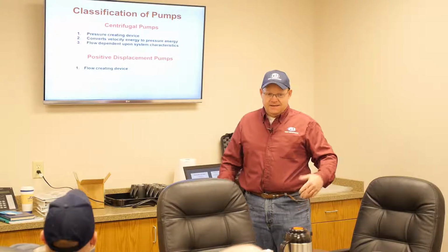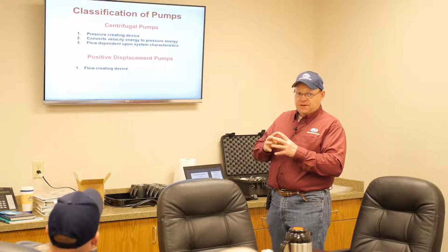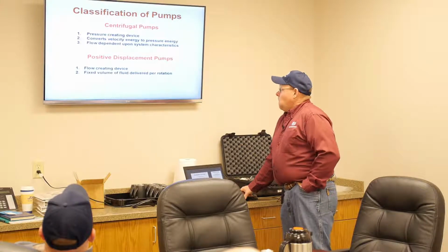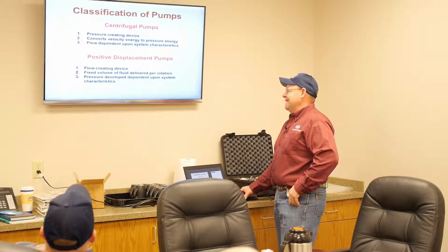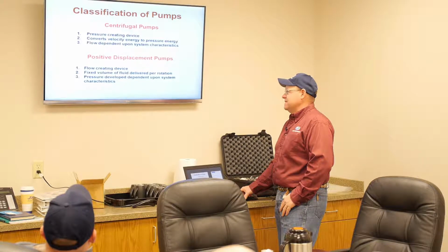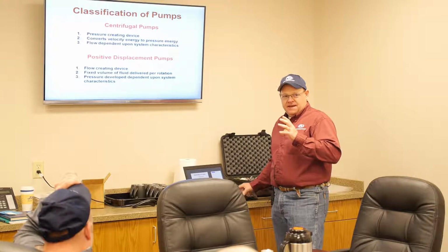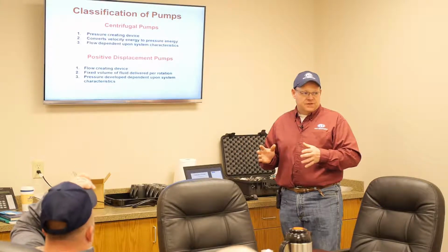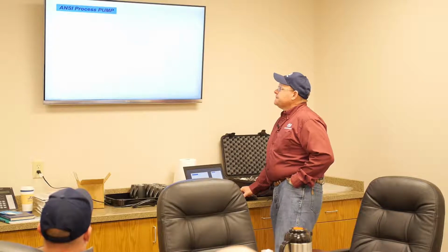There you go, Viking, again a gear pump. Every time that thing rotates, you're going to get a certain amount of flow. Is that making sense now, the differences? It's a fixed volume per rotation. Sorry, I got ahead already. Pressure developed is dependent upon the system characteristics. It's only going to provide whatever pressure it takes to get the fluid from point A to point B. It's not going to produce pressure itself. As we go through this, keep that in mind.